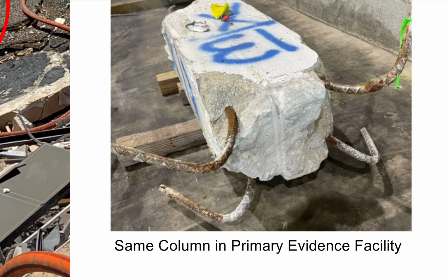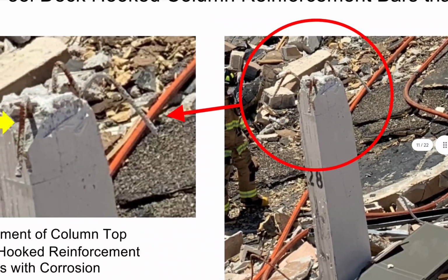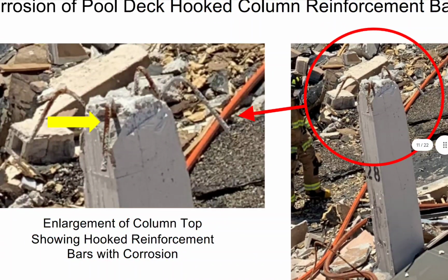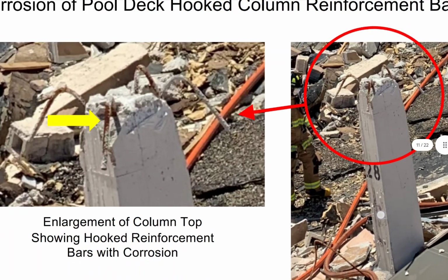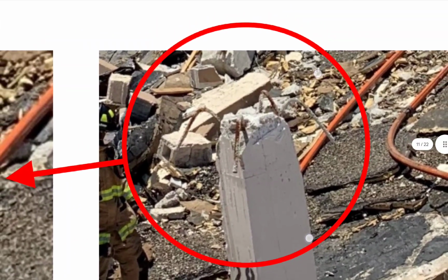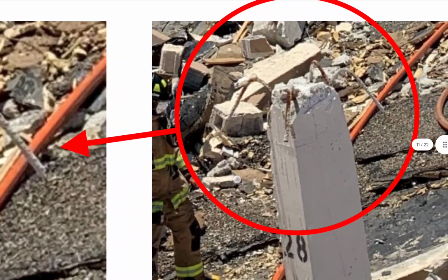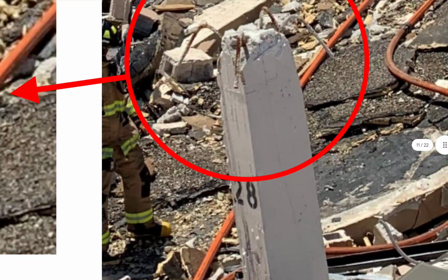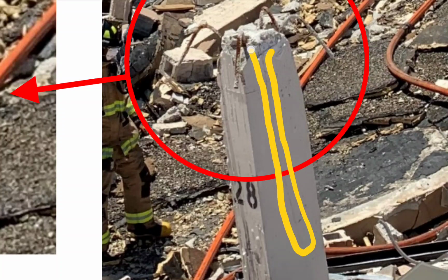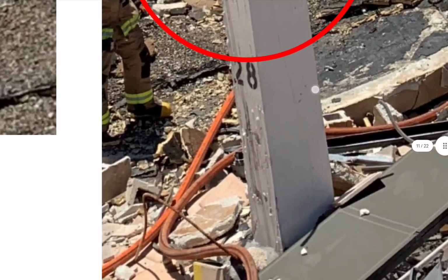This had concrete on top of it. This is the head. All right, it had concrete on top. What else did it have on top? A critical shear zone reinforcement, that went down here. It looks like the scratch marks. So the break would have been over here, and I might find some rebar standing over here.